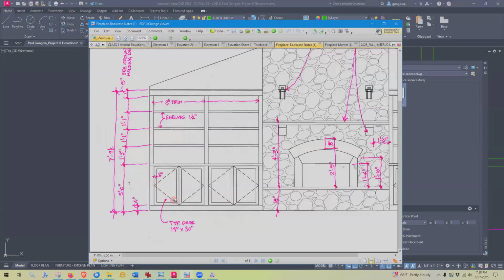Those actually aren't on the door, but they represent something to whoever's looking at my drawing. Is that how they open? Exactly, correct. This tells whoever is looking at my drawing how this door opens, where the hinge is. So where is the hinge? Where these two lines meet, this is telling the contractor or the mill worker or whoever's going to be working on your drawing that the hinges are on this side of the door.